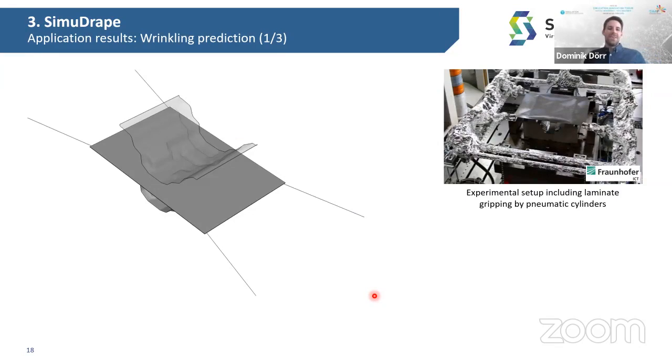Okay. So much so far on the theoretical background. I'd like now to come to some application examples. So what you can see here is a generic geometry. This was used to investigate how forming behavior looks like, and also to validate thermoforming simulation. We also have some crimper elements here. These crimper elements are modeled here using so-called translator elements in Abaqus.